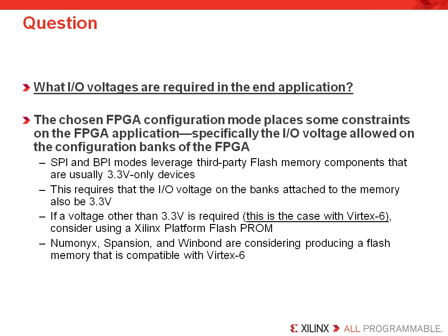In this case, it is important that the designer be aware that the FPGA configuration pins are reserved and usually placed in a single I/O bank. Thus, depending on your configuration mode, that will require all the I/O pins in that bank to be compatible with a 3.3 volt device and may limit where you want to place your other I/O pins on your FPGA. So plan your use of the bank pins associated with your dedicated configuration pins a little carefully.